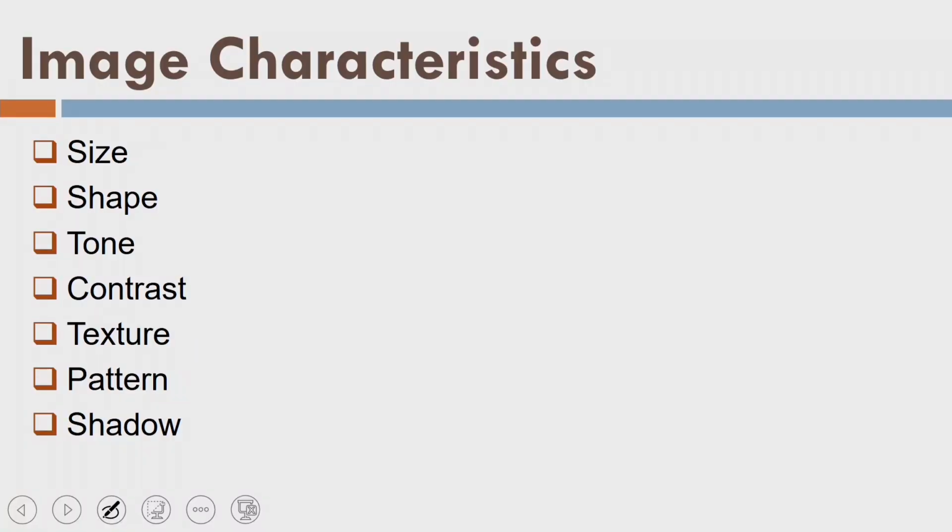Once we learn how to do it, we have the radar image, we have some noise, what we call speckle, and then we remove the speckle, then we calibrate the image, and then we find out the quality of the calibrated radar image, so that I can use it for topographic mapping or any other purpose in higher surveying. Once we get a calibrated radar image, then we should have some reliable properties about ground features. So what are the properties?